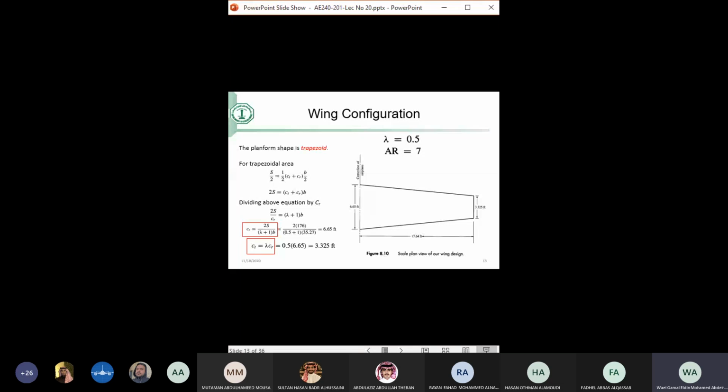What do I mean by this? When you say the wing area S has a certain value, we know it's the planform area. It is this area, of course, multiplied by 2 because of the other half. But when I say Cm, the coefficient of moment, is equal to the moment divided by 1/2 rho V squared S C, what is C?